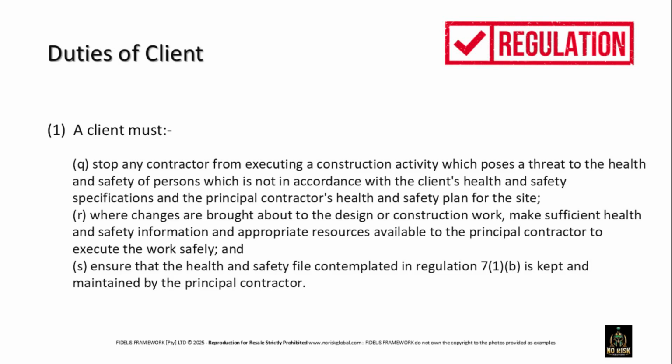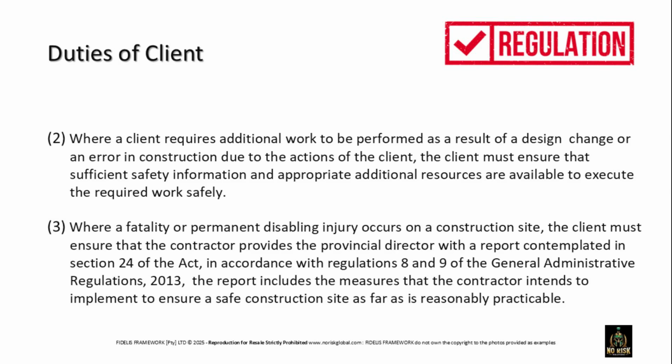Clients must stop any contractor from executing unsafe construction activities. They should ensure changes in design or construction work are communicated and maintain the health and safety file. When additional work is required due to design changes, clients must ensure safety information is available. In case of serious injuries, they must report to the provincial director and implement measures for a safe site.